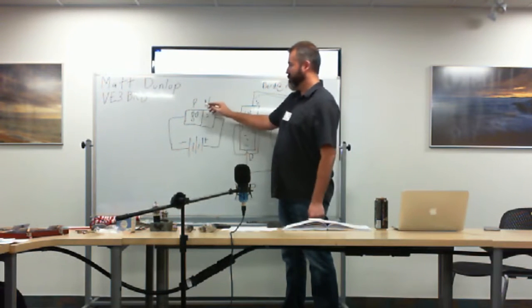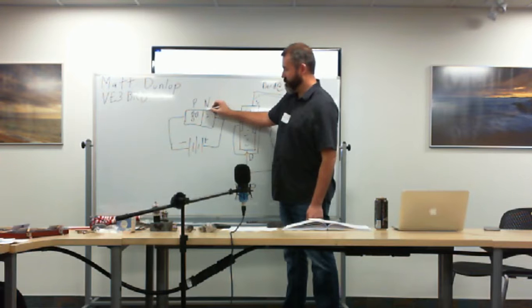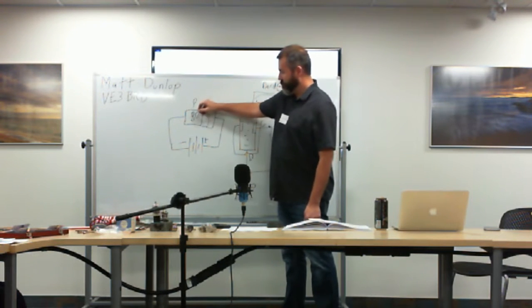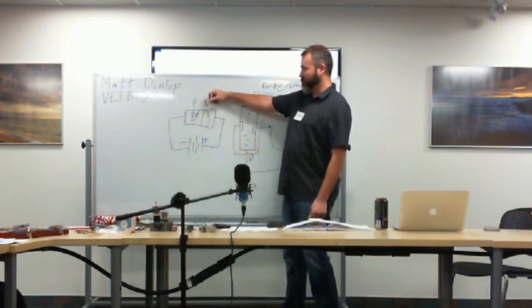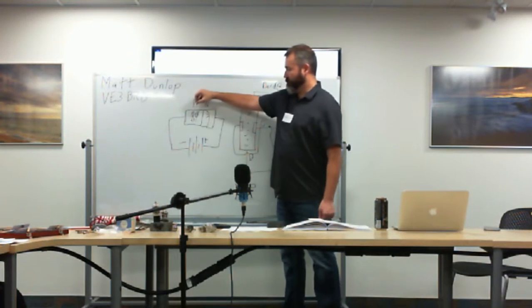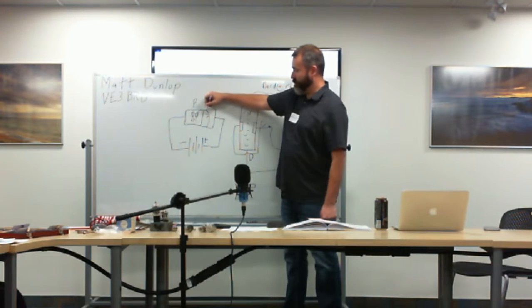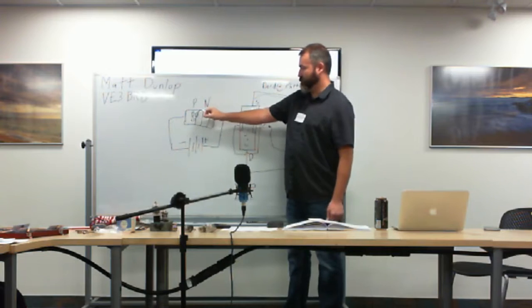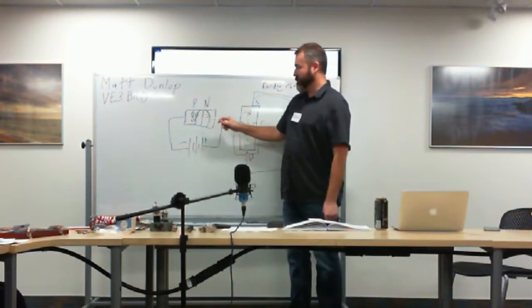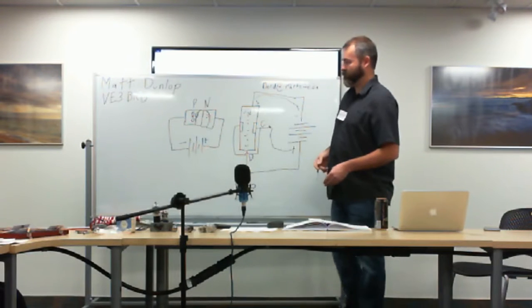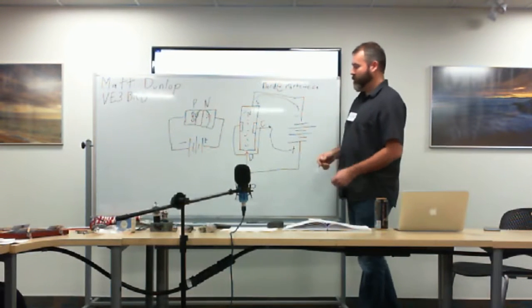This is reverse biasing this junction, which actually causes the depletion zone to grow, because it's drawing the electrons from the N material towards the positive and vice versa on the opposite side. So it actually causes this zone to stretch, thus making the material in the center an insulator, and the bigger the insulator, the more it stops electrons from flowing through.